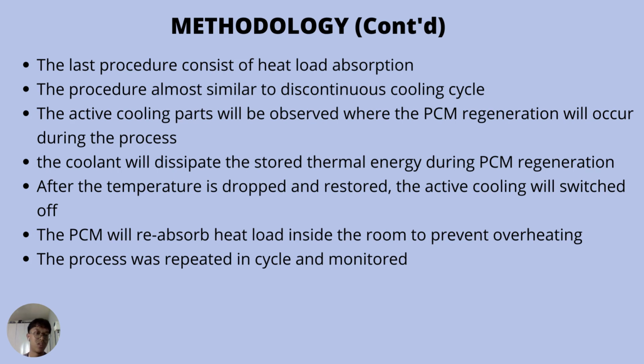And after the temperature has dropped and is restored, where the cooling is happening, the active cooling will switch off when the temperature reaches a certain point, and the phase change material will reabsorb the heat load inside the room to prevent overheating. And this process will be repeated in a cycle and monitored, and the results will be recorded.